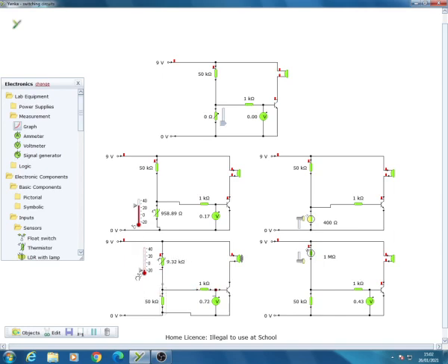I can't get it to drop down low enough. So I can mess about with this resistance down here. So if I make it 100 kiloohms, like that, I can see I'm still not making any difference. So what I could do is drop it down maybe, see what difference that's going to make. And I've managed to drop it down to 0.71. I don't really want to drop this resistor any lower than that.